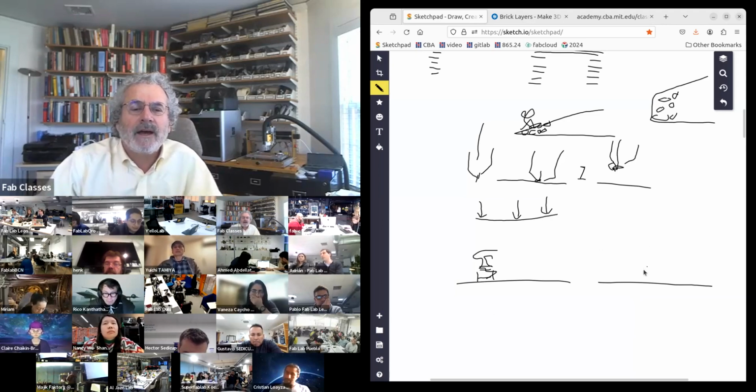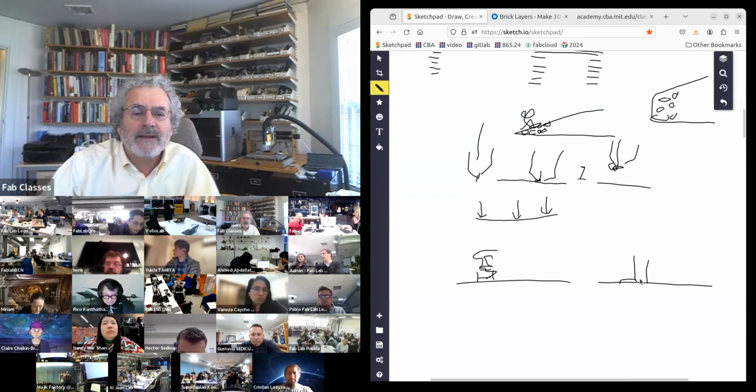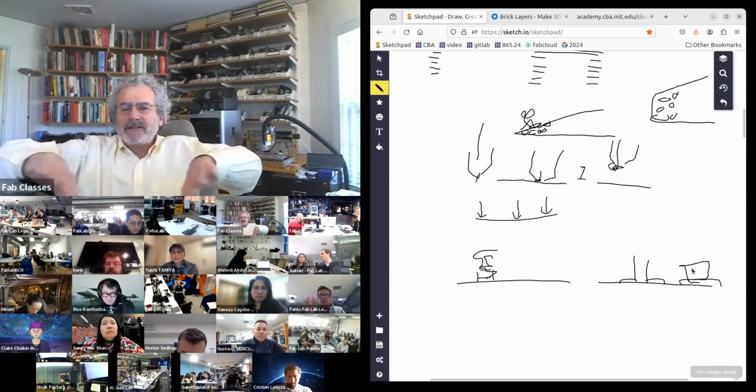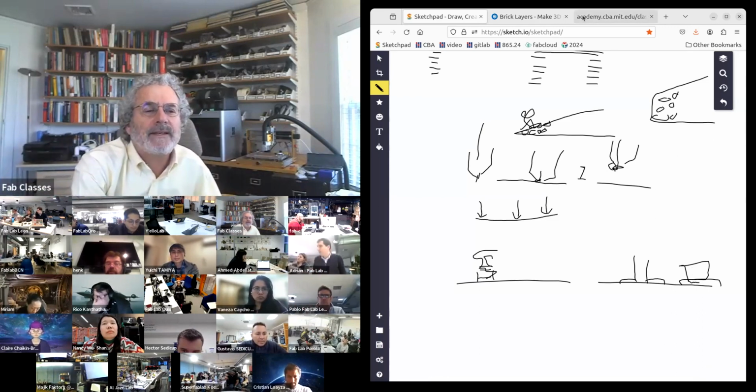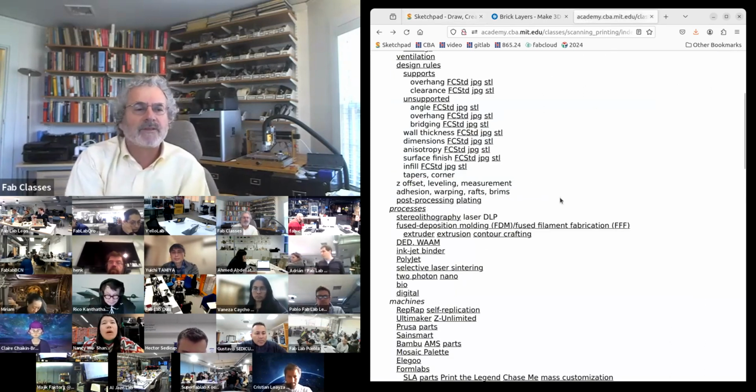And then one thing you can do is what's called a brim, where you print a lip that goes beyond your print that's easily trimmed off but improves the adhesion. You can also make what's called a raft, which is a layer that supports your part that goes from the bed into the geometry of your part. And so if you have trouble with bed adhesion, rafts and brims can help with that.